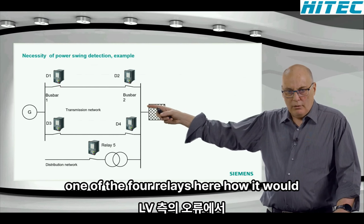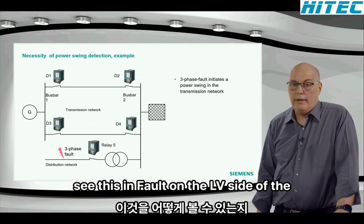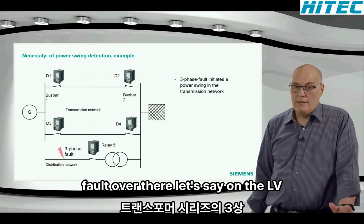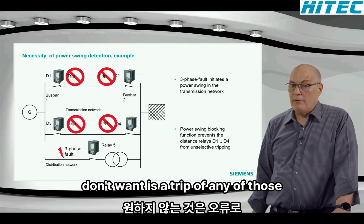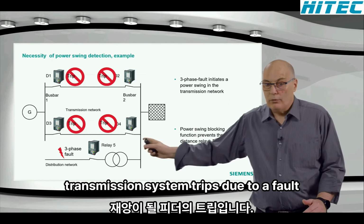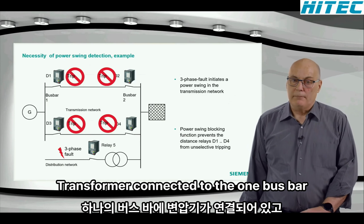I can't remember which one of the 4 relays here, how it would see this fault on the LV side of the transformer. So the 3-phase fault over there, let's say on the LV side of the transformer. And what you don't want is a trip of any of those feeders. That would be a disaster if your transmission system trips due to a fault on the LV side of a transformer connected to the one busbar.